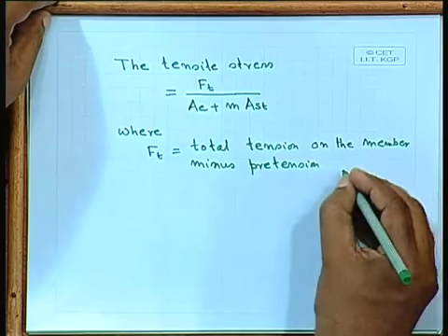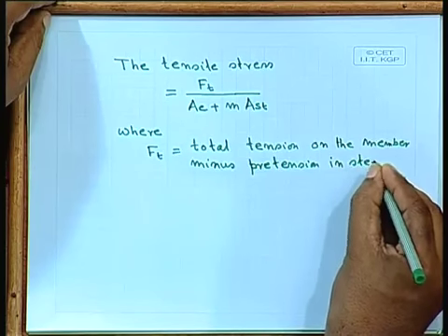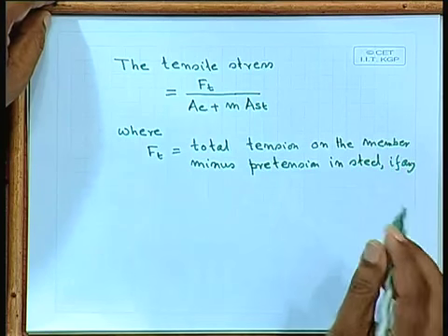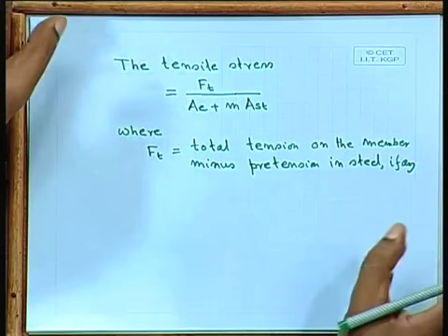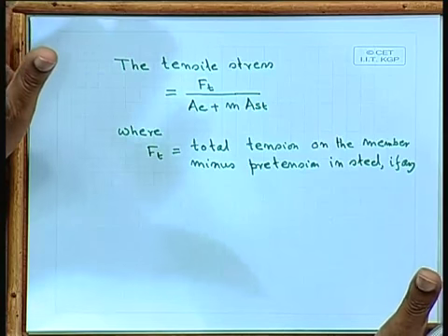This pretension, I am coming to explain, if any. Pretension means that if you have any pretension and then you are applying the load, then the tensile stress will be increased. So that means you have an initial value of tension, and obviously you have to deduct it.